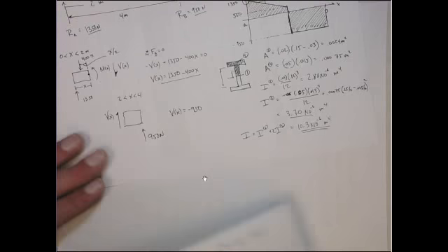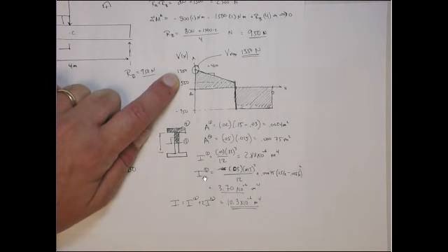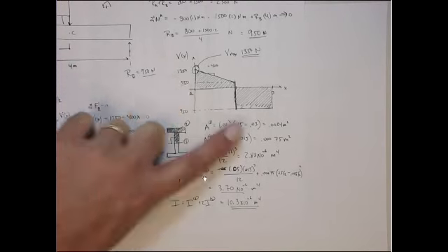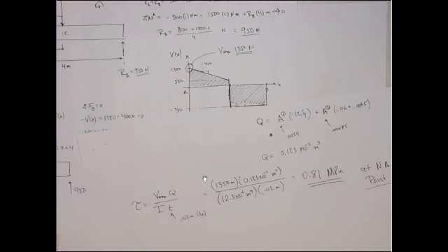When I did it by hand here, I got a Vmax of 1350. And I can actually check the V at A and the V at B. So I know the V at B is negative 950 and the V at A is 1350. So let's check both those values. Granted, I don't use the V at point B in this problem because that turned out to be less than V at A. But you should check that it's still the same, because there might be another problem where actually the B will be the critical one.